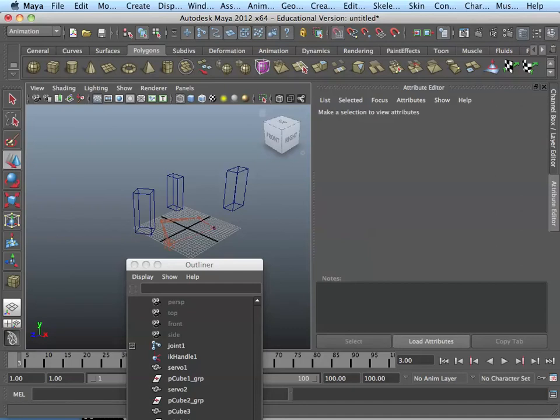So these guys output between 5 and 6 volts. We can tweak them a little bit. They're probably set to 6 because these things will handle 6. So you'll see on all of these, from the black and white cable, it's split: whites positive, blacks negative. So you then just connect them up.